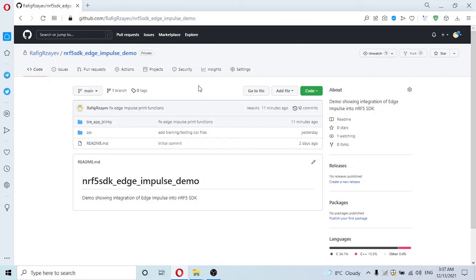Then once a project is built, we have a bunch of object files, and we can include the object files in the Segger Embedded Studio project. And this way Segger wouldn't need to compile any C++ code. It will just use the objects directly. So the only thing required by Segger Embedded Studio is to fix the include directories.